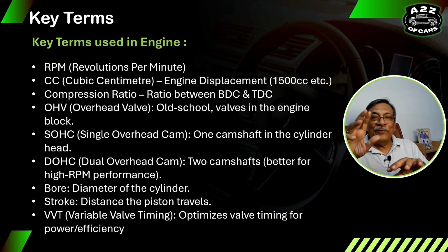That's why if you look at the speedometer of especially two-wheelers, now most of the four-wheelers have VVT so there you won't find this, but in two-wheelers you will find that after say about 60-65, they must have marked red, and before that it is green or blue, economy. And from here the economy goes down. Why? Because your fuel is getting wasted, it's not being used. You are pressing the accelerator, the fuel is going, but it is not able to enter inside the cylinder because the valve is closing and opening very fast.